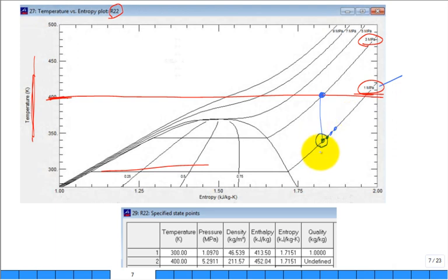No. It's still superheated. It's going to be pretty warm. The first thing I'm going to do, as I move it through the condenser, is cool that superheated vapor until it gets to the point at which it's going to start to condense down near 300 Kelvin, and then I'm going to condense it. That's not a good design choice, is it?